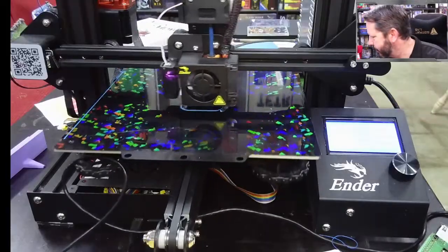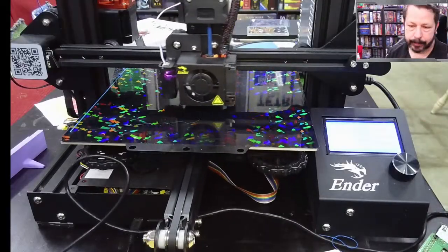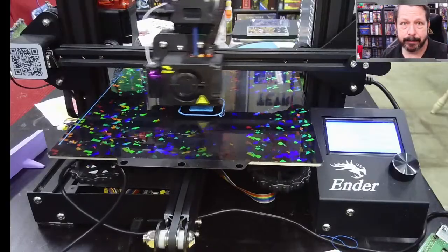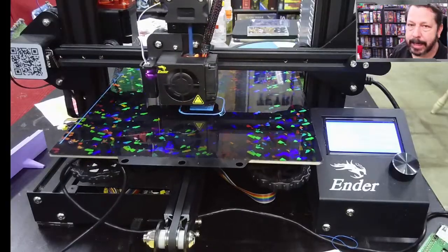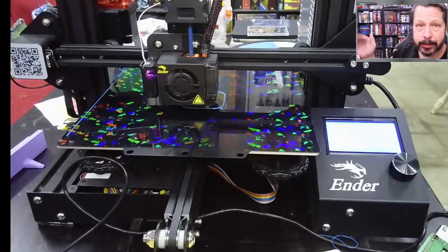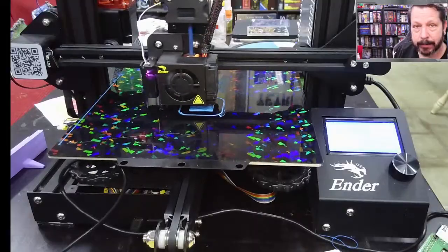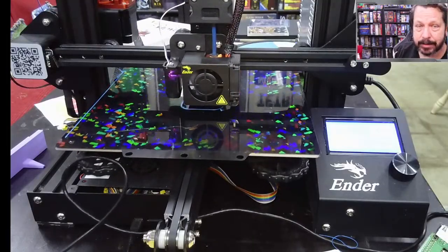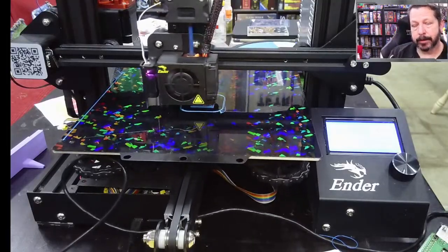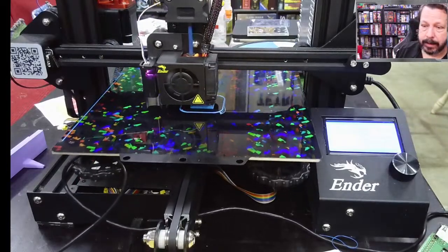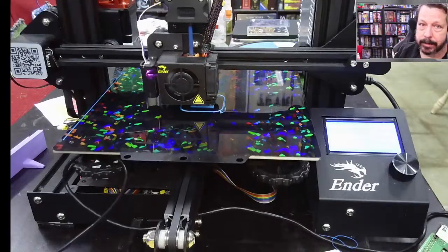So these little layers don't matter too much. Sometimes if you print too fast, well, there's a lot of things that can happen, but one thing you might have to do is raise your printing temperature, because it has to push out more material, which means it's got to melt it faster. And so if you do increase your printing temperature, however you do it, you probably need to print at a little bit higher nozzle temperature.